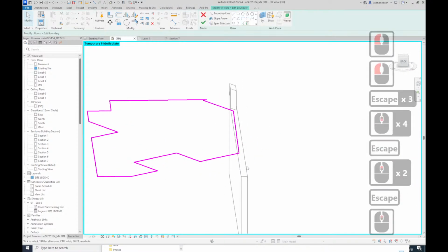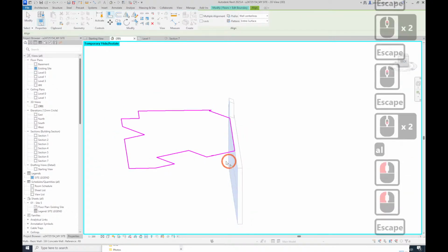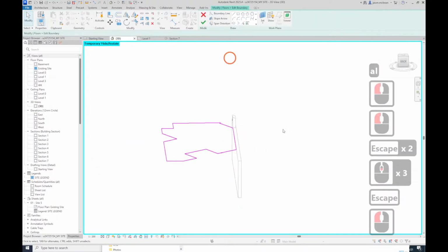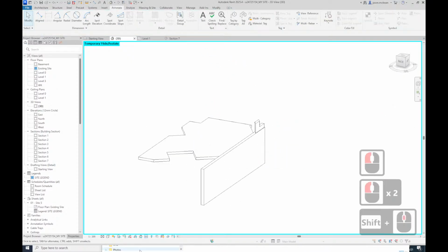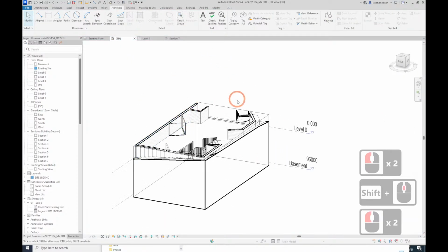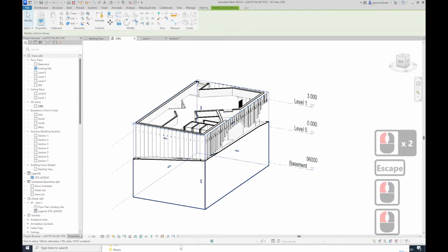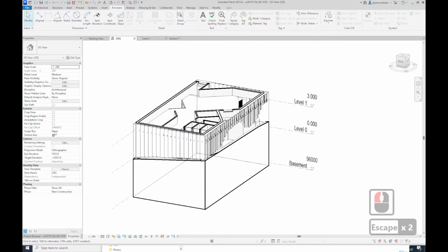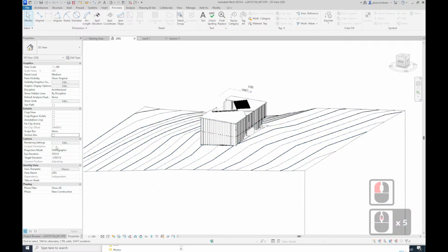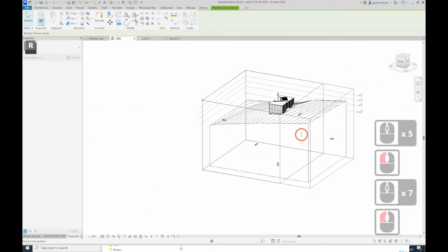Here you've got 2 walls, so just be careful, and that's why I don't like to use 2 walls sometimes. Just like that, sorted. And now you can go and see this, and now if you want to reset temporary height. Now the only trick with this section box, to reset your section box back to normal, you must just go to properties, and say section box on and off. It'll show everything, and then you just go back here again, and then it resets it. Then you can drag it again.